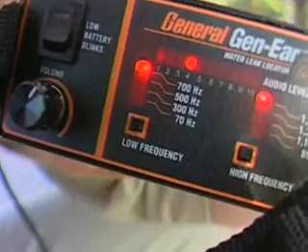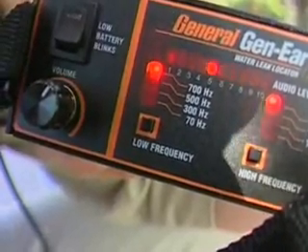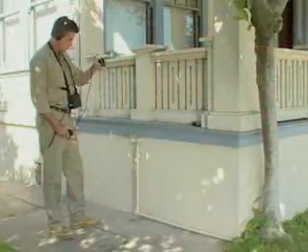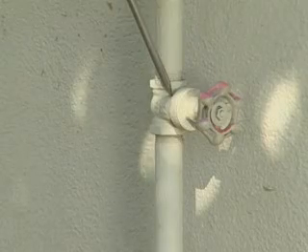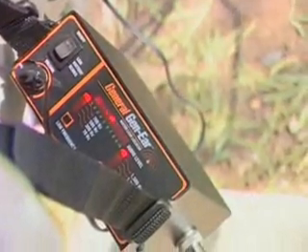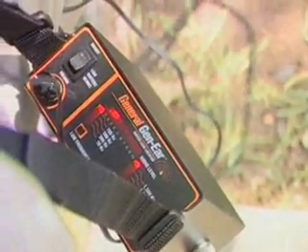If you hear the sound of a leak, check lines running in all directions from that point. The leak location is usually found between the loudest and second loudest survey locations. Now, you can begin to narrow your search and isolate the leak.